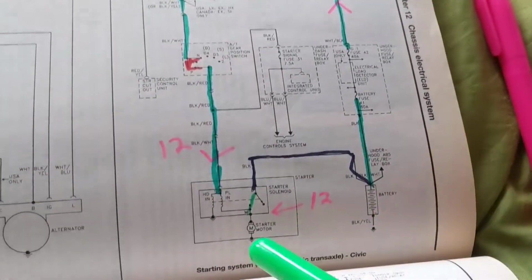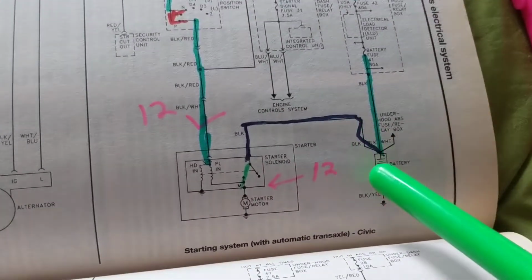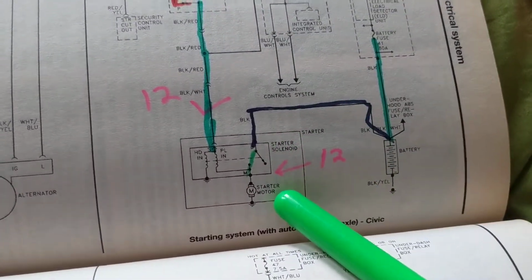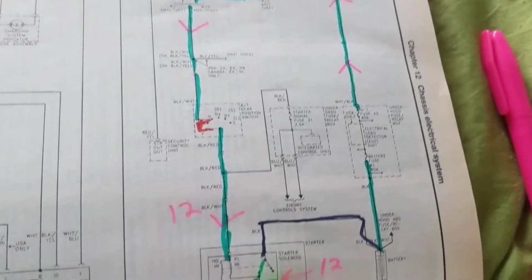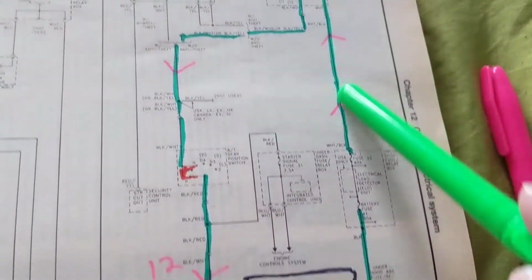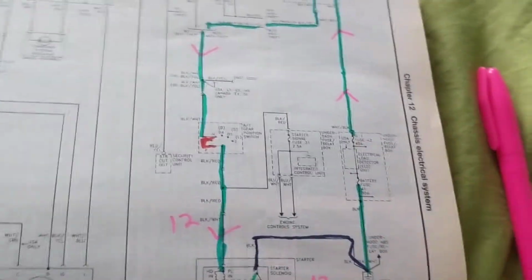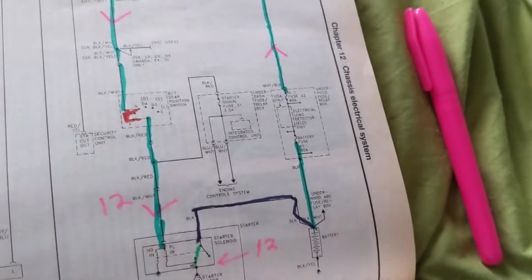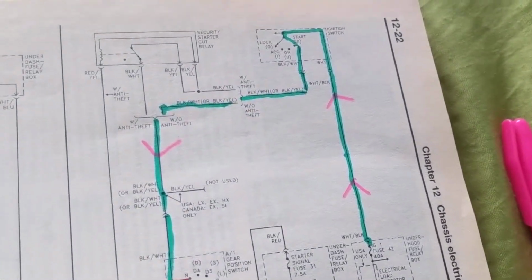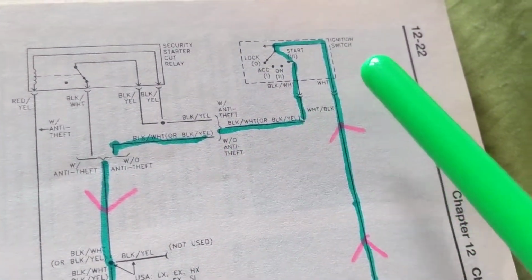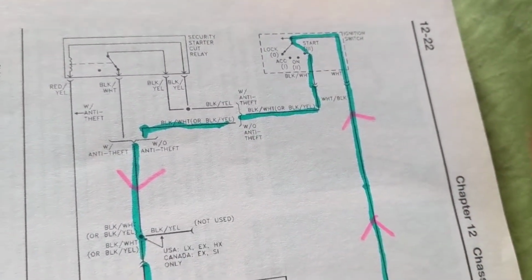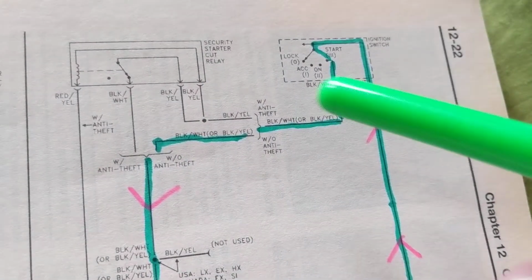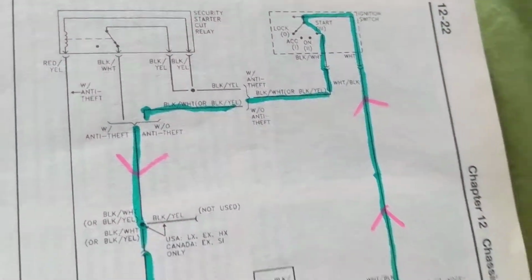So therefore, where would we start? We know that 12 volts has to go to the starter motor, but before that, it has to be engaged. That happens by a solenoid. So we have to go back to the path up here. Now, this is the point that I wanted to make. If you recall before, in which position of the ignition switch do you start the starter motor? It can only be one position. That position is the start position.